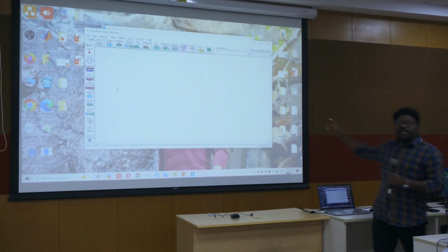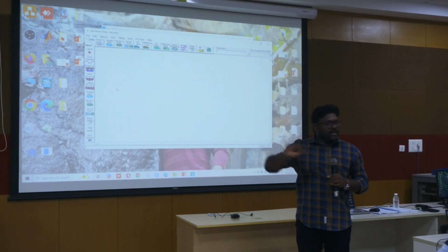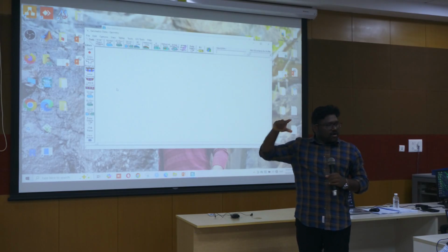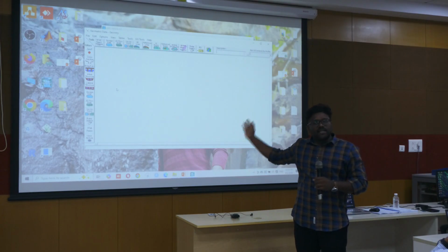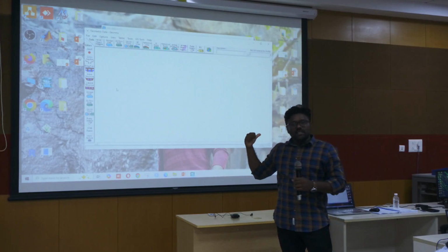In this geometry, we need to draw the river center line, bank lines, flow paths, cross sections, everything. Previously, when HEC-RAS started in the first version, there was no GIS layer inside HEC-RAS.